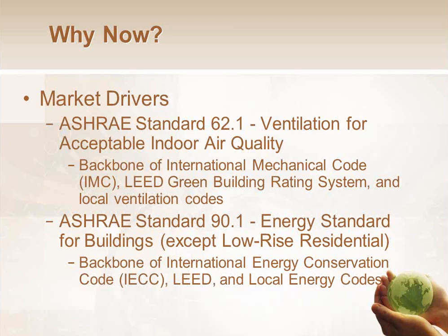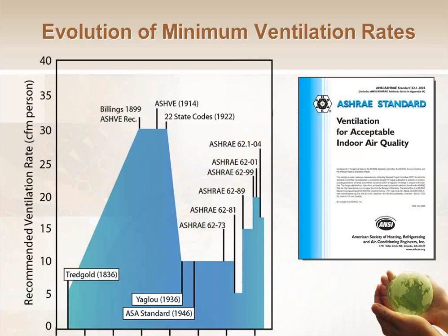The other main standard at play is ASHRAE Standard 90.1. This is the standard that sets forth our energy conservation rules for the country. Both of these standards feed into the applicable international codes, and those codes get adopted by local municipalities. So for example, in Illinois where I'm at, we are using the International Energy Conservation Code 2012 version, and it is based on ASHRAE Standard 90.1 2010. And as far as ERVs are concerned, the language is identical.